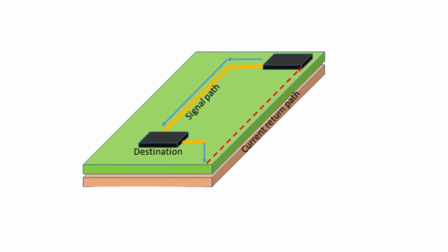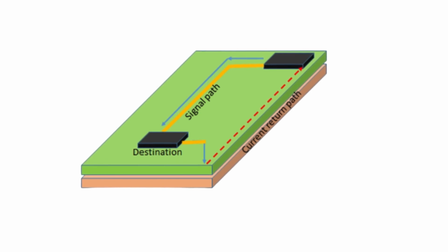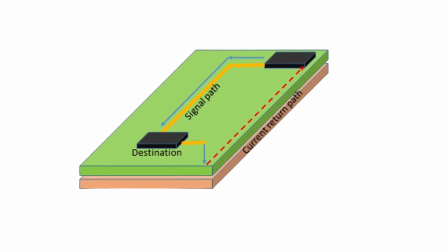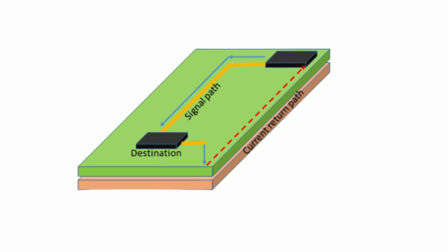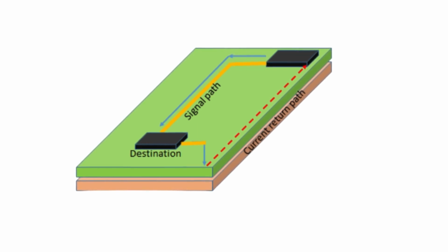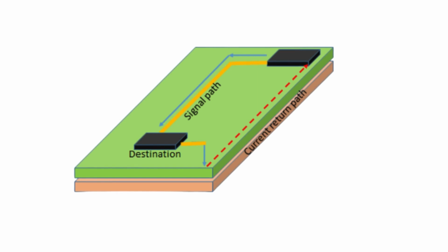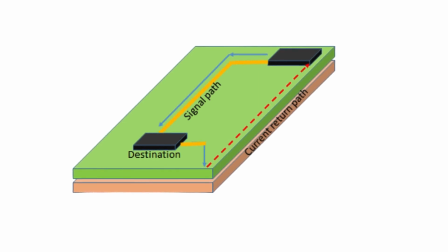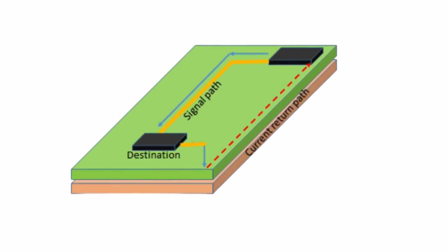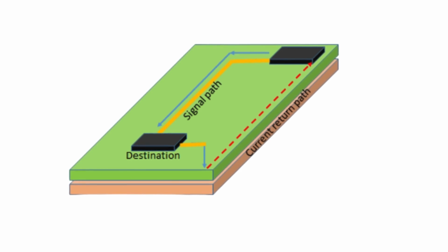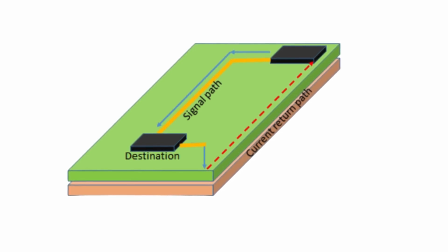Here's where engineers get burned: the return path. Fields don't care about your schematic symbol for ground. They care about the physical path that completes the loop. At RF, return current follows the path of lowest impedance, often right under the signal trace, because that minimizes loop inductance.